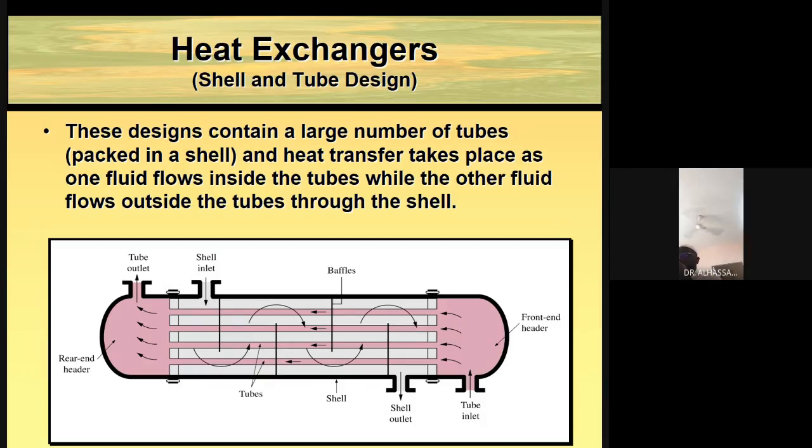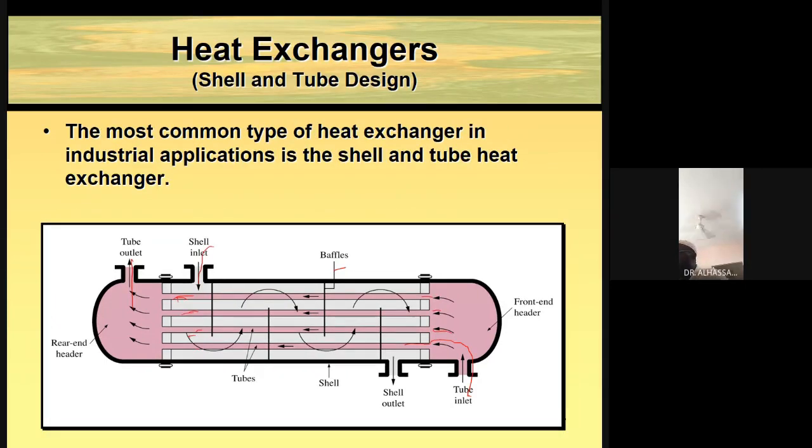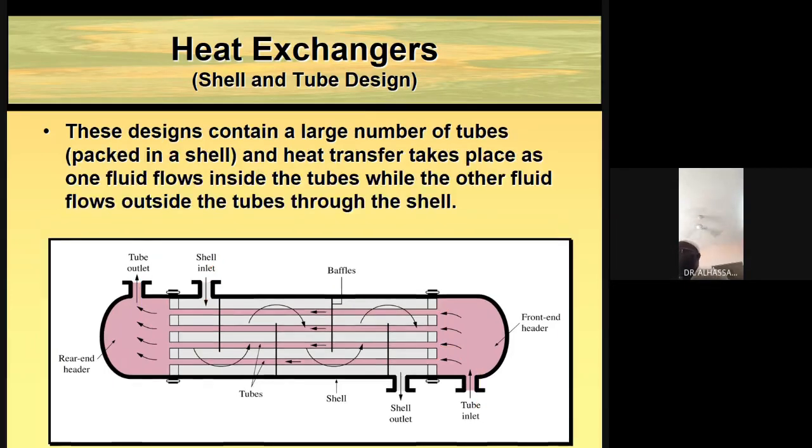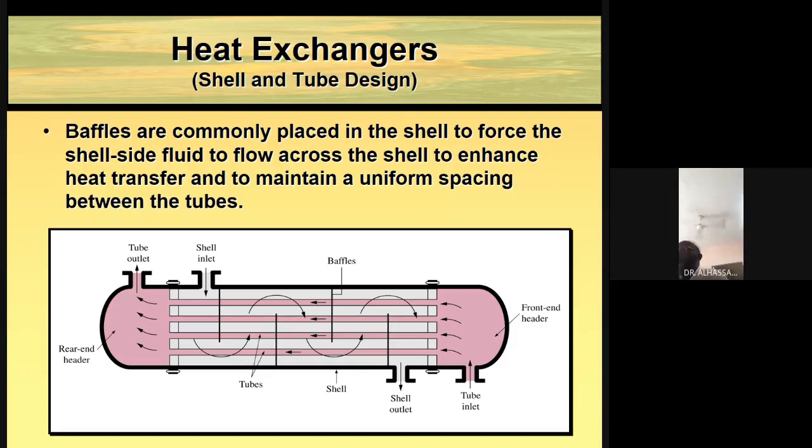The same thing applies to this particular one, and the same thing over here. Baffles are commonly placed into the shell to force the shell side fluid to flow across the shell to exchange the heat.